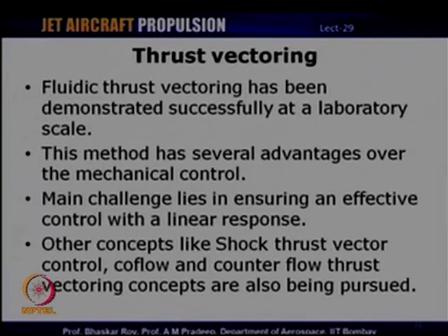In fluidic thrust vectoring, on the other hand, it involves injection of a fluid or suction of a fluid. Though this has not really been used in an actual aircraft, it has been demonstrated very successfully in lab scale, and there are several advantages over mechanical thrust vectoring, in the sense that here you do not need to have those complicated mechanisms, which obviously increase the weight of an aircraft, and that is one major advantage with fluidic thrust vectoring.